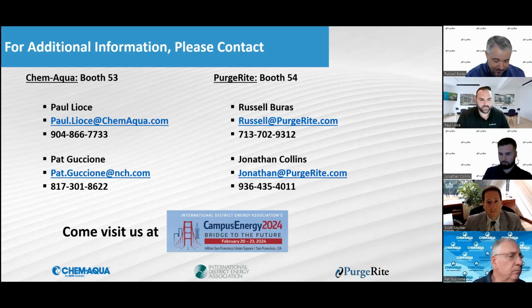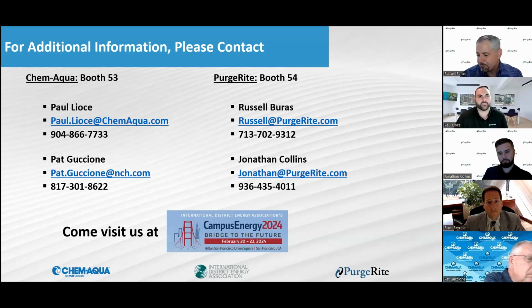So one, if you're looking at the quality of your makeup, if it says that we need to get iron on our final flush down to 0.5 ppm, and maybe your domestic water coming in has 0.25 ppm iron in the makeup just because of the old pipe from the city or something going on there. Well, then you need to know that right away because you'll never really be able to get that flushed all the way down to that low point, right? So you're trying to chase that, but you have so much coming in with the city water.